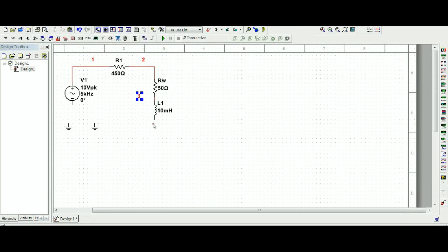So let us finish the wiring here. I'm going to come from this component over to this ground, and I guess I'll set a corner here, and I pick up a net name there as 0. Why? Ground. Ground is always net 0. Moving him over a little bit and running him up, also have a net name of 0. So anytime you see two net names are the same, they are connected.